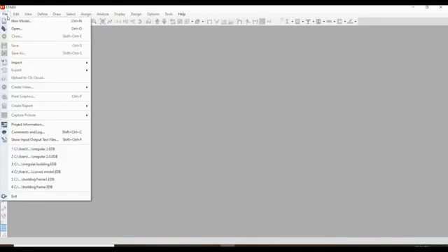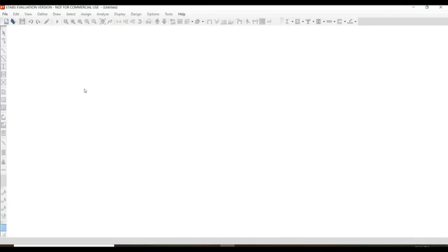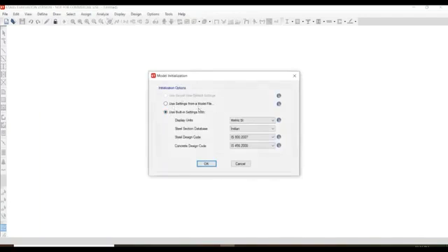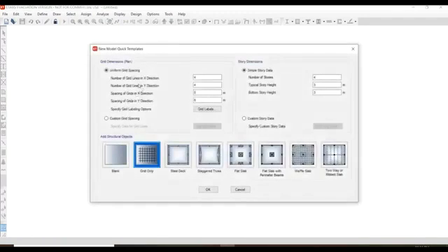Today we're going to see, first, we need to design the model. For designing the model, first open ETABS and open the new model. When you open the new model, you will get a pop-up, and make sure the settings are made accordingly. Display units are in SI system, the steel section database is of India, and the codes are IS 800 and IS 456. Click OK. And then now use the X direction grid lines.